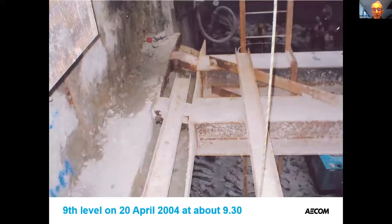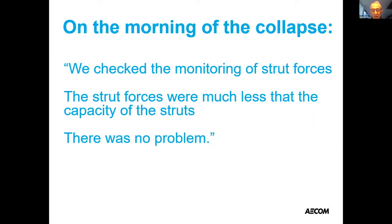And this shows, on the morning of the collapse, 2 such connections which had already swayed, and the engineers on site were aware that this was a problem. They went up into the site office because there were strain gauges on the struts which were being monitored on an hourly cycle, displayed on the computer in the site office.